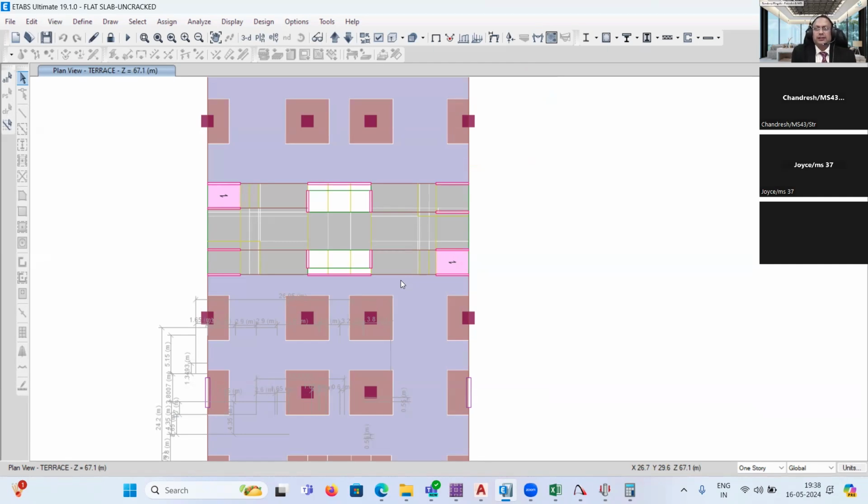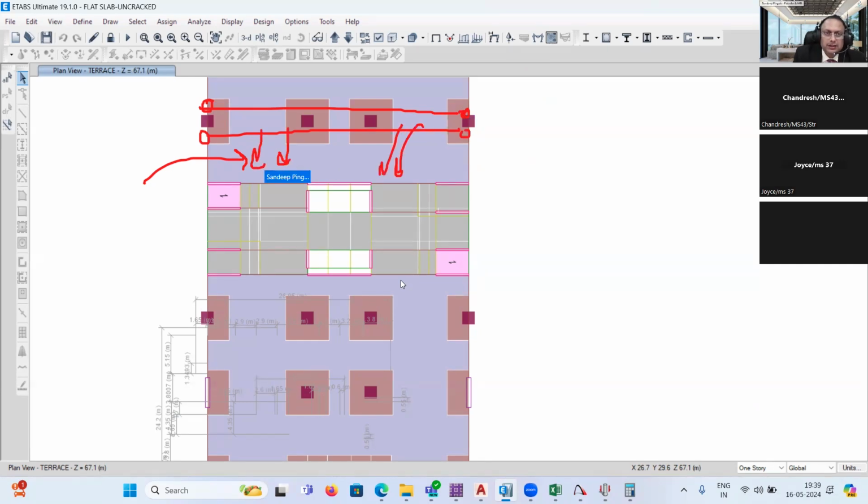Yes. See, post tensioning, I'll tell you, even I'll be prone to the post tension, particularly here. The only problem is the capabilities and the calibre of the post tensioning people. If the post tensioning consultants are giving certain issues, if they are not tying these things properly, the entire deflection, everything will be at stake. So we generally ask this risk to the client, do you want to take it? If they say yes, go ahead with the PT. If they don't want to take it, then go for RC. RC is a long-term perfect solution.